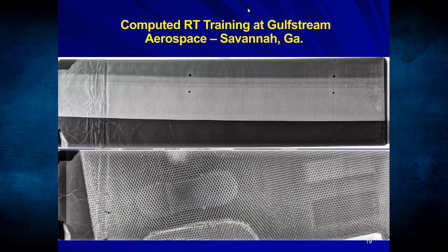So this is a computed radiography image from a composites manufacturer. On the left side here, you can see the structure is clear. Other than some artifacts over here. These are fingerprints. These are called artifacts, but pretty much this is a pretty clean area. But if you go over here, to my left, anybody can see that this composite is wrinkled. The manufacturer was squeezing this component together to try to make it fit, and you ended up with wrinkles, and that is not acceptable.